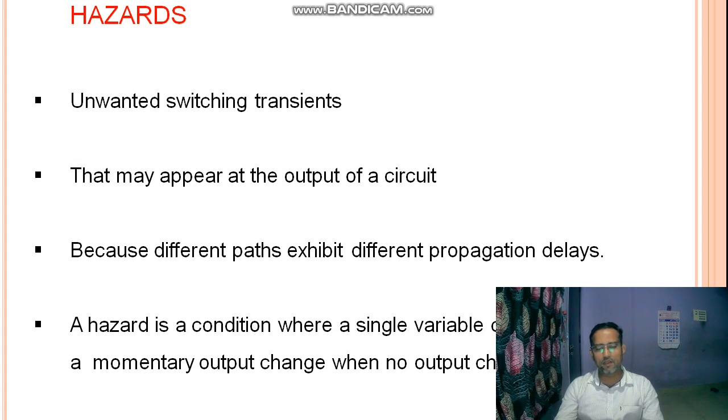For example, if you take 0 as the input, it propagates continuously, and then the time in between adds a 1. Then if you take 1 as the input, it propagates continuously, and then an error of 0 appears. So the 0 to 1 and 1 to 0 transitions appear differently, and an error fault is created in the switching transition of states. The exact name for it is hazards.